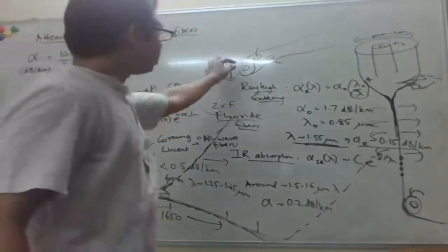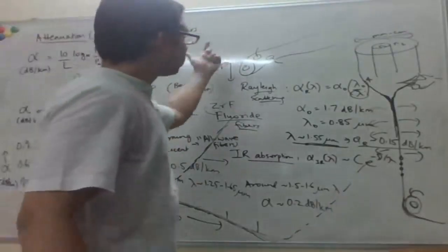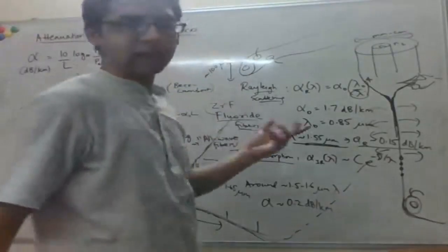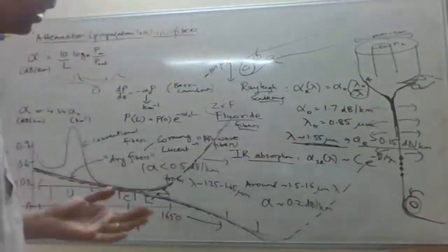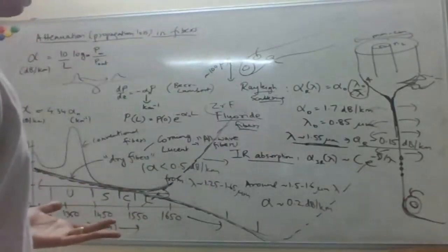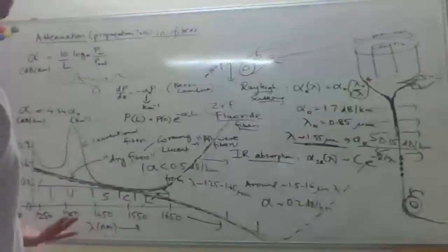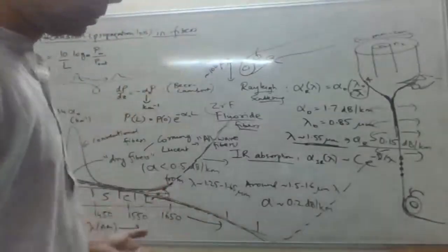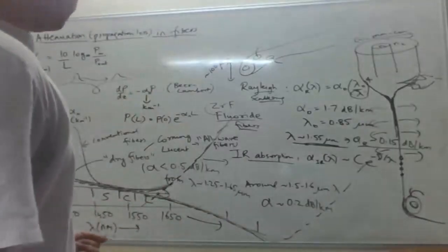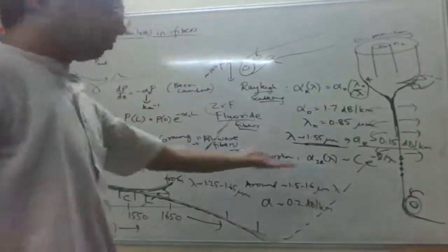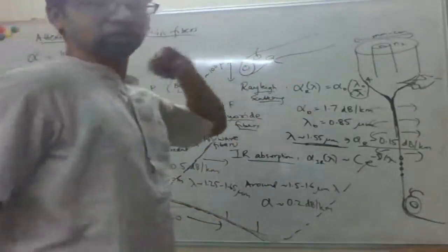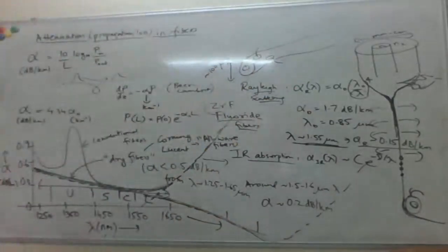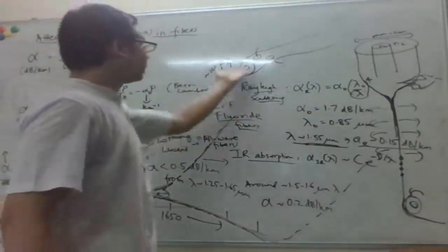There we'll see how changing the core size, or the refractive index of the cladding, changes the modes which are supported and what is known as dispersion. But the loss is independent of those things because it just depends on the material, which is glass.